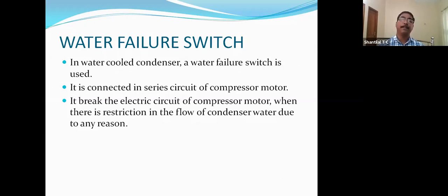Okay. So this is another safety device, the water failure switch. The function of the water failure switch is to stop the motor when water pressure is reduced in the water cooled condenser. When water pressure is normal, the switch will keep the system on.